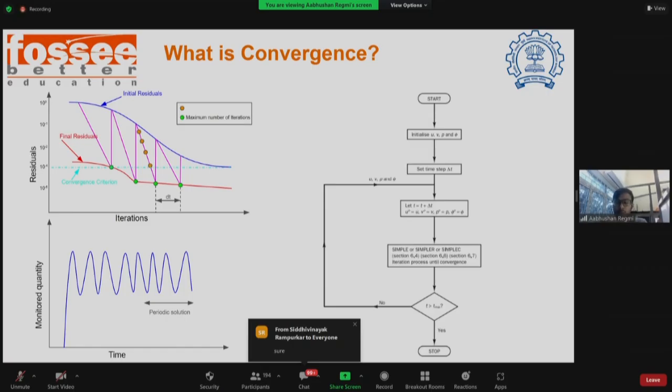Here, what we are doing is, before starting the simulation, initializing all the variables to 0. So when we put this value, the internal field value, into our equation, you'll get something that is remaining, some leftover value. That value will come as the initial residual.